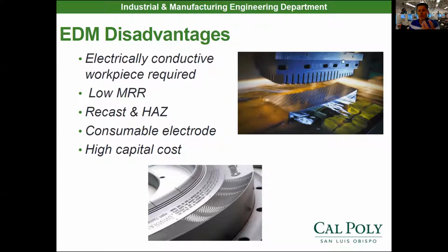So we have to be able to keep machining electrodes and keep getting wire in order to keep this process going. Now, if you look, here's some tire molds. So this is a Continental tire mold. You see that right there? So the sinker die EDM was able to sink in the wording into this tire mold and this little, I guess it would be a tread. And then you can kind of see here's another tread out here on another piece of a mold. So they're used heavily in mold making.